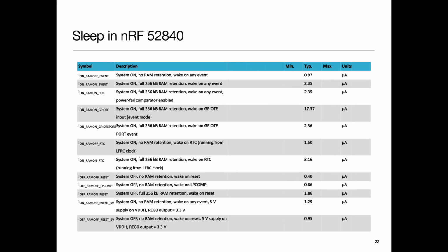Now think about, you have a decision making thing to do, right? Should I go to the deeper sleep mode with lower power consumption but a higher cost of coming out of it? Or should I go to a shallower mode? So what do you think? How would you decide that? This is what would be called a sequential decision making problem, right?